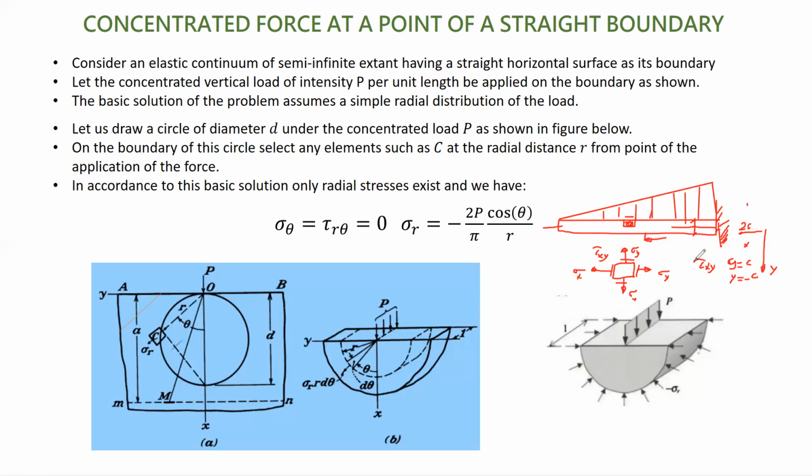So the shear stress tau xy should be equal to 0. In the equation where you define shear stress with some constants, make that shear stress 0. You have two relationships that need to be satisfied on the top and the bottom so that the shear stress will be 0. That's one thing.